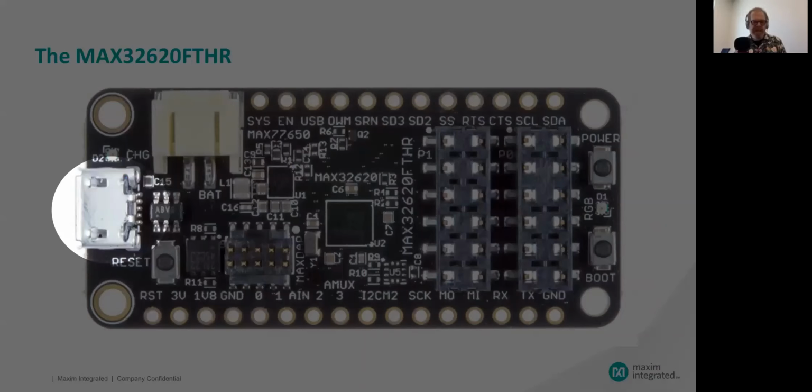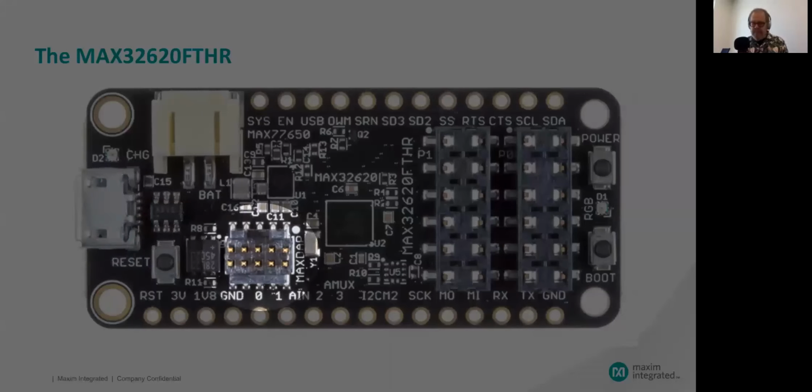So for better or worse, that's the nature of the port. Okay, let's talk about the SWD connectors over here. If you're not using the embedded bootloader, then this is the primary way that you'll program your board. You'll plug a debugger right there. We include a connection to the console UART via this connector also. So in one cable, you have the loader, debugger, console, the whole thing.